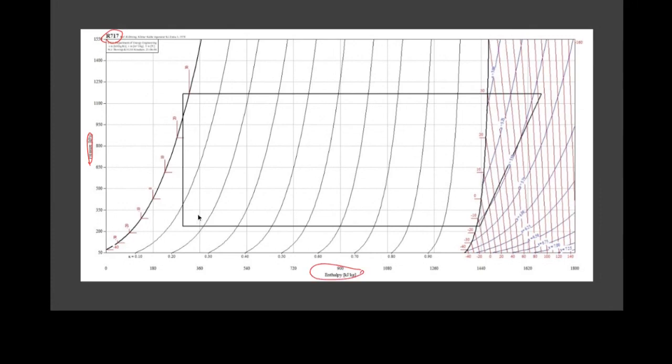You know about pressure enthalpy diagrams, you've used them for steam, and in your academic supplement, there are, I think, 3 different charts for 3 different refrigerants. Every refrigerant has its own chart because it has its own specific thermodynamic properties.